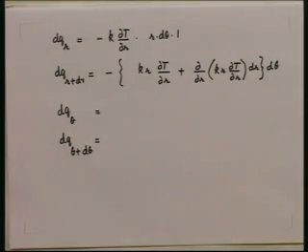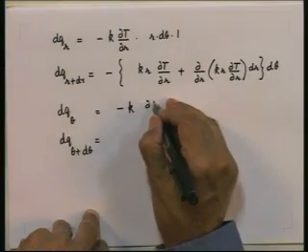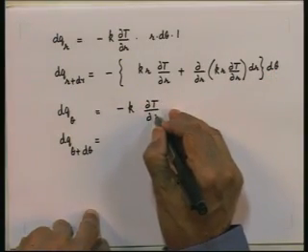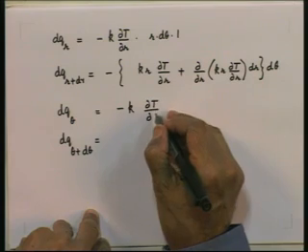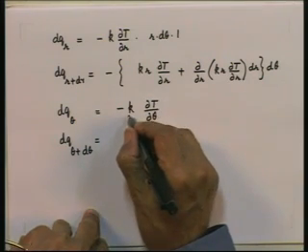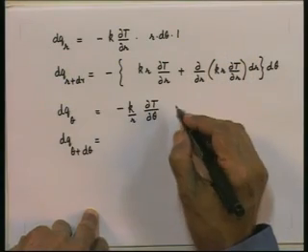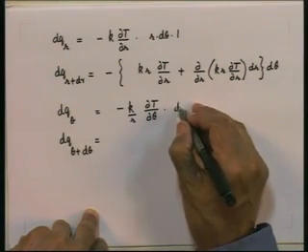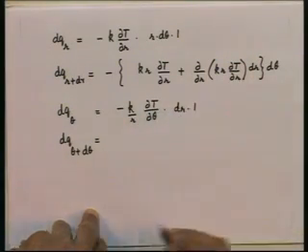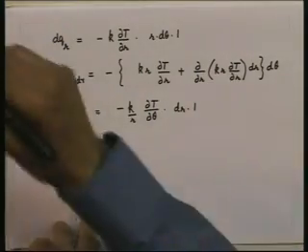For dq theta we will get minus k dt d theta, because we want a variation gradient of temperature with distance. So, it will be minus k dt by r d theta, the whole thing multiplied by area, which will be dr into 1. And if I move a distance, an angle d theta forward, that is the distance r d theta forward, I will get